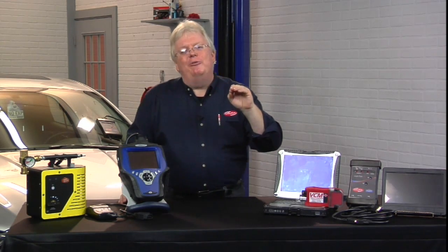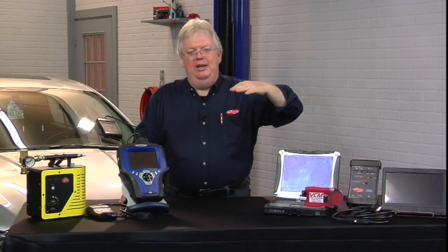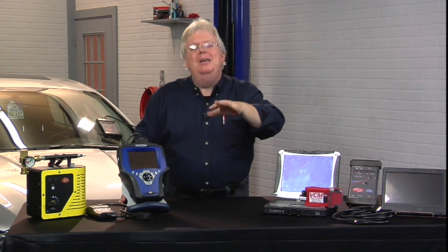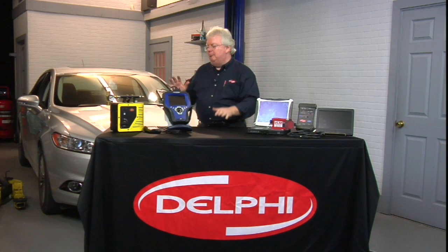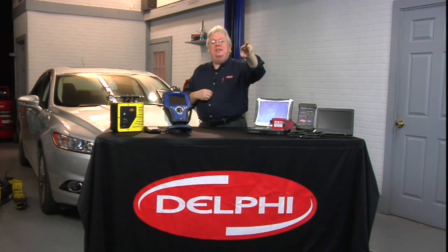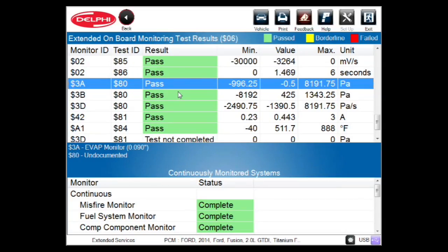It's telling you that before the solenoid failed, we ran all those monitors and they were all good. A couple of them were close, but they were all good. So what do we do here? We would diagnose the circuit problem, the 443 electrical issue, not a leaky issue where we need a smoke machine, but the electrical issue. Diagnose it, repair it, make notation of all this information in mode 6 that we see here, especially the ones that were just barely passing, and then clear the codes, drive the vehicle, run those monitors again, and now see where everything lands.